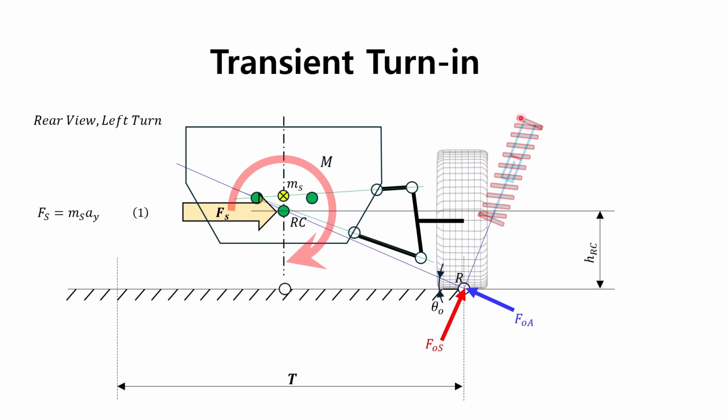Accordingly, in the initial steering time range, the understeer tendency is less compared to a steady state turning, so the vehicle turns in smoothly. If the initial understeer is still large, the understeer tendency can be reduced by increasing the damping of the rear shock absorber. The shock absorber's response speed is slower than the link, but faster than the spring and anti-roll bar.